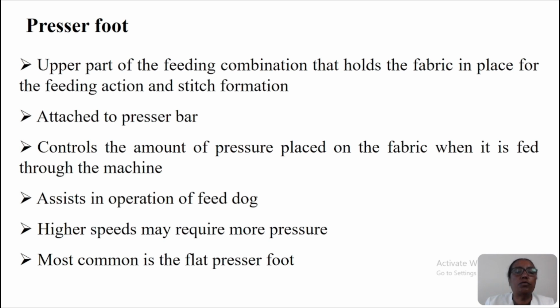This pressure foot helps the feeding mechanism by holding the fabric in place for the feeding action and stitch formation. It is also attached to the pressure bar. It controls the amount of pressure placed on the fabric when it is fed through the machine. It also assists in the operation of the feed dog.